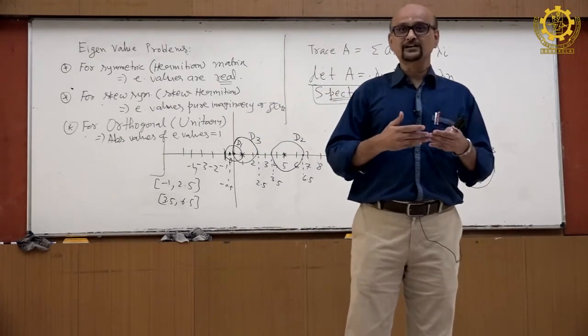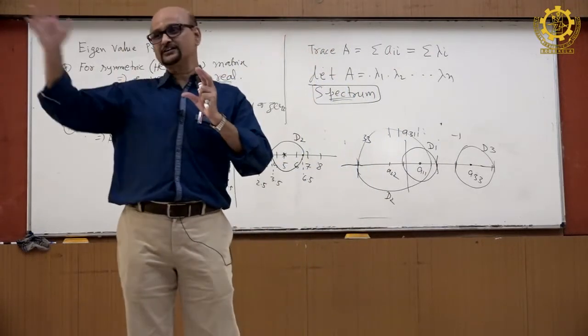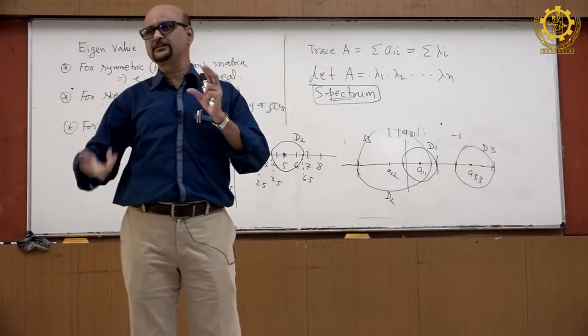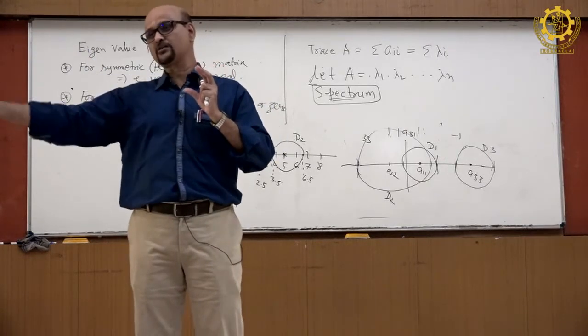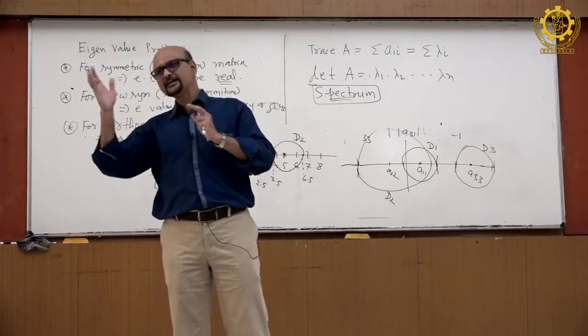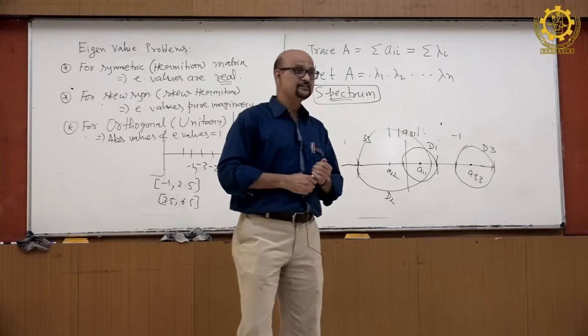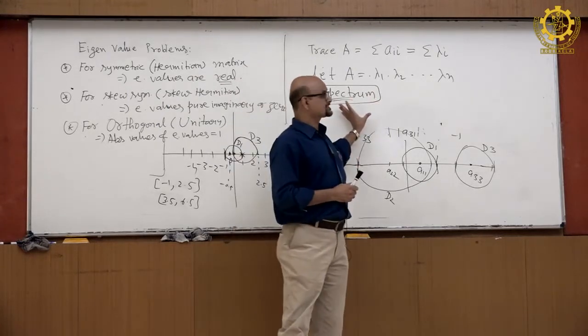So, what do I need? I need the natural frequencies, because I cannot expect what force frequency will come, because it depends upon the power of the wind or the power of the earthquake. But for a certain range I can have the safeness. So the main aim is to find this spectrum.